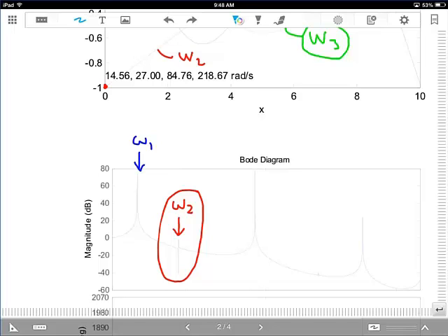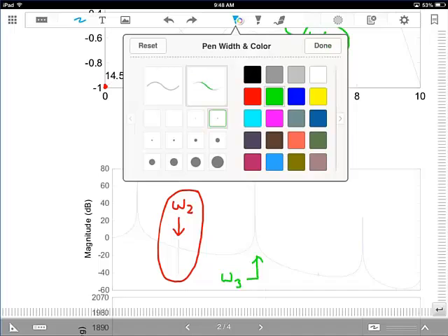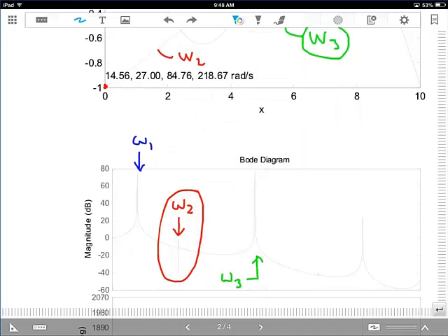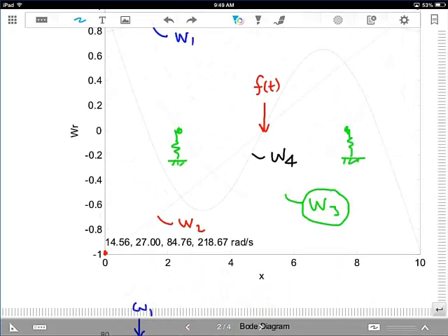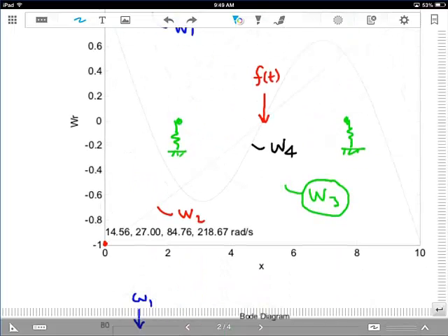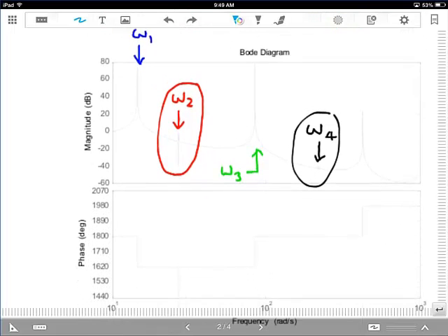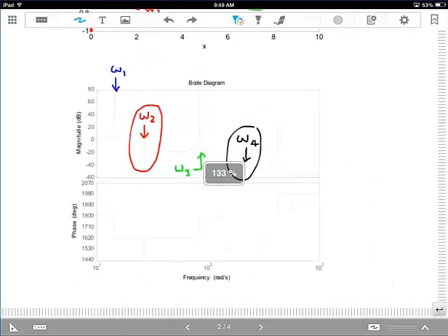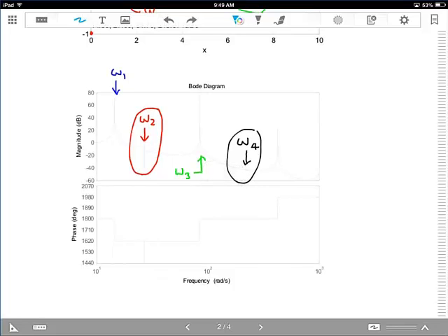Now, omega 3 comes through loud and clear because it can be forced and sensed at the boundary. But here's omega 4. Again, it looks like it's kind of canceled out, and that's because there's sort of this pole zero cancellation, because W4 also goes through 0 at the center of that beam. Okay, so everything looks very reasonable from the viewpoint of the boundary spring problem.